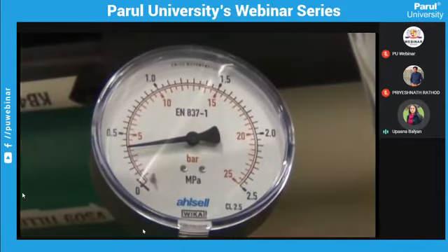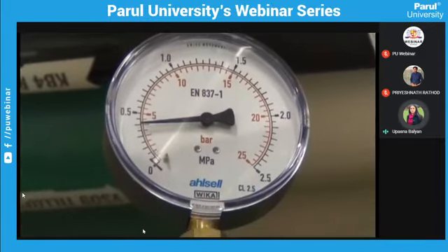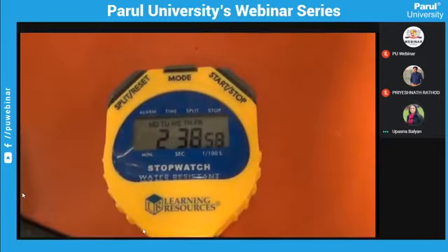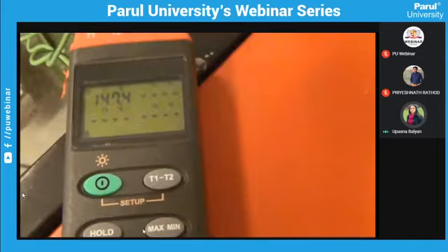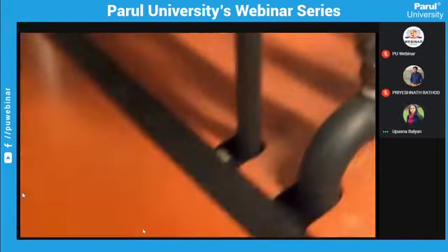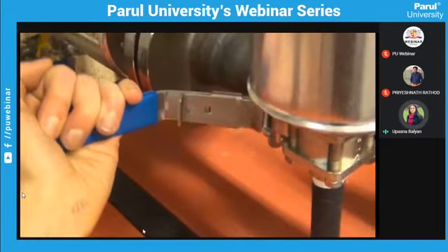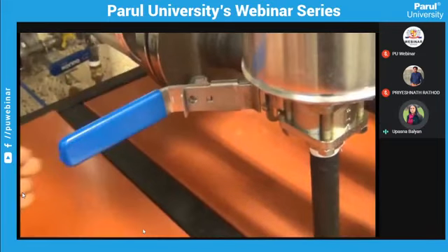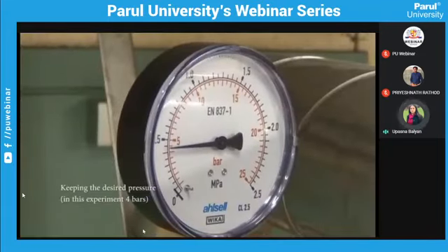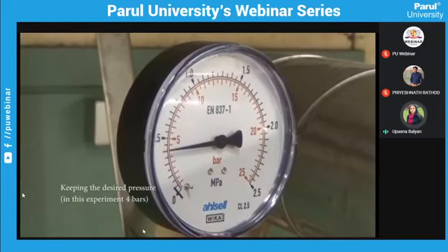You're just opening the feed, the steam pipes, so that we can put the steam inside, and the time should be 20 minutes. So you are providing the pressure up to 7 bar for 20 minutes. Through this, you can open the steam inside the pipe so that it can travel to the chamber.